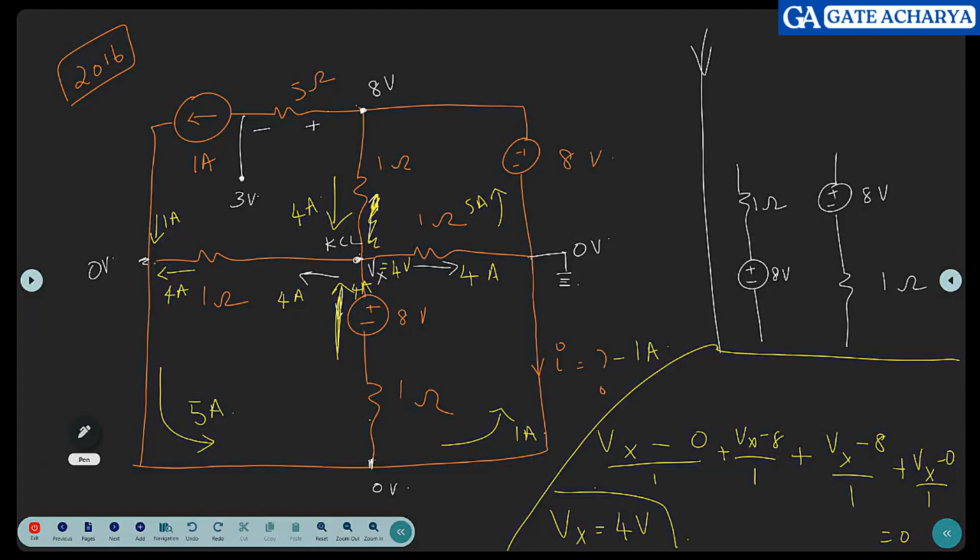How do we explain for people who did not get it? Where did we start? We started with a simple KCL equation. To write this KCL equation, the first observation is we had this problem of a resistance and a voltage. So we made sure with KVL that you can replace them. If they are in series and there is no branching tapping out in the middle, you can definitely replace them. After you replace them, it looks much simpler.